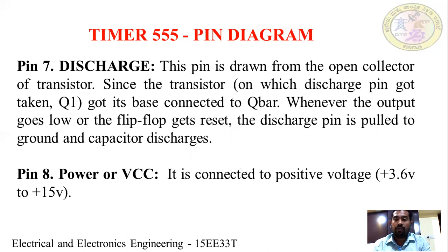So whenever the output goes low or the flip-flop gets reset, the discharge pin is pulled to ground and the capacitor discharges.